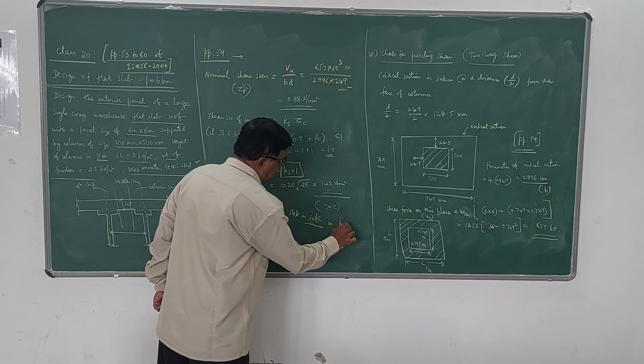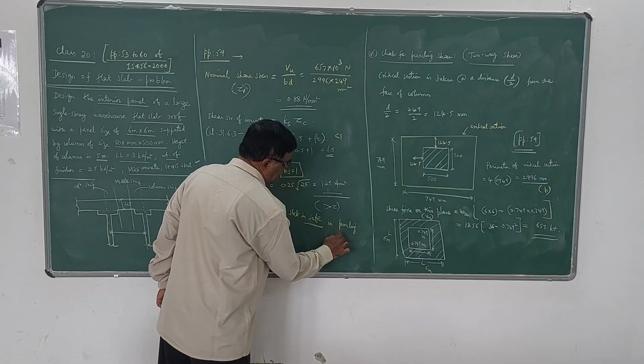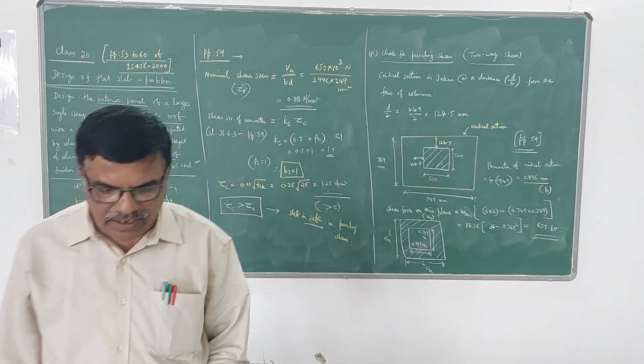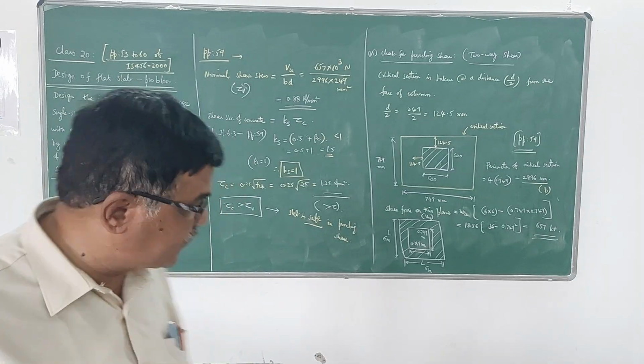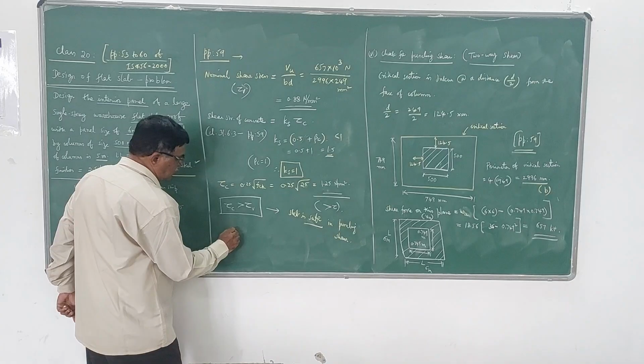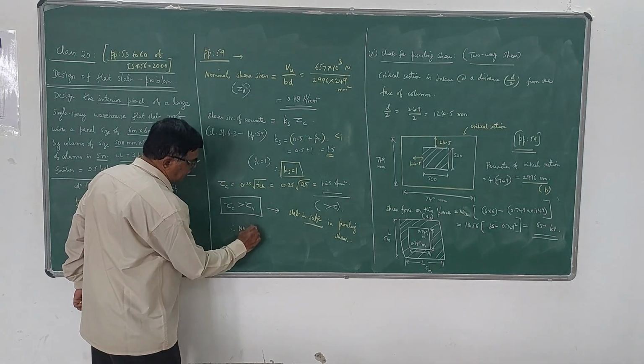So this is how we have to check. Normally in most cases the shear check is automatically satisfied. Therefore no shear reinforcement is required.